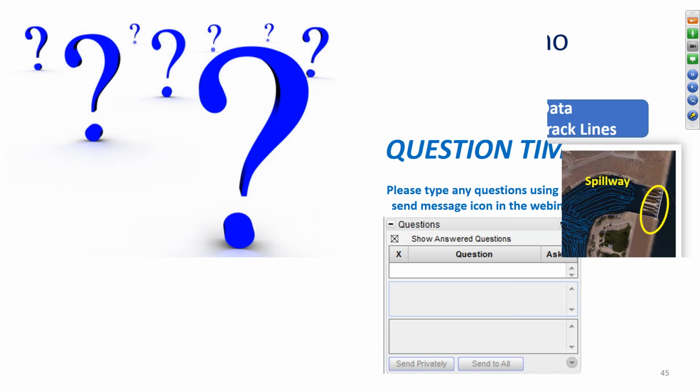On the other hand, if I'm using a lower frequency instrument or a multi-beam instrument, I have more ability to penetrate through vegetation and soft sediments. So it comes down to knowing what the limits of your instruments are, using the right instruments, knowing what's going on in your river, and then designing a study that can answer the questions that you're looking at.